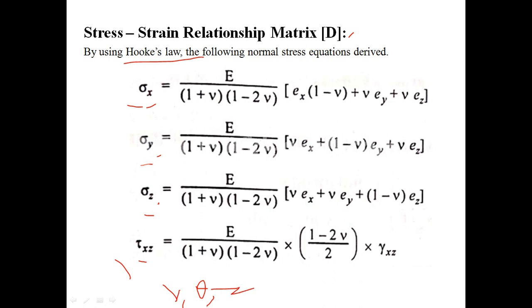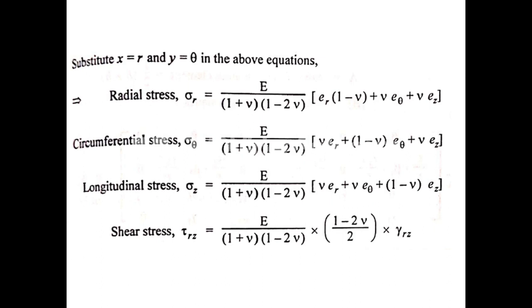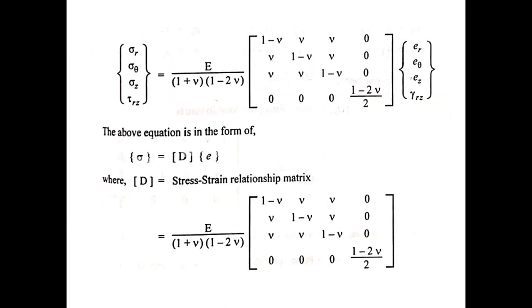Okay guys, and finally we have the stiffness matrix K. We already know the governing stiffness matrix equation: K is equal to the volume integral of BᵀDB dV. That dV is replaced by 2π r̄ A. So what is r̄? It is the average, (r1 plus r2 plus r3) divided by 3. We apply those values. We already know the B matrix, we already know the D matrix, which are applied here. We will get the K matrix, the stiffness matrix for the axisymmetric element.